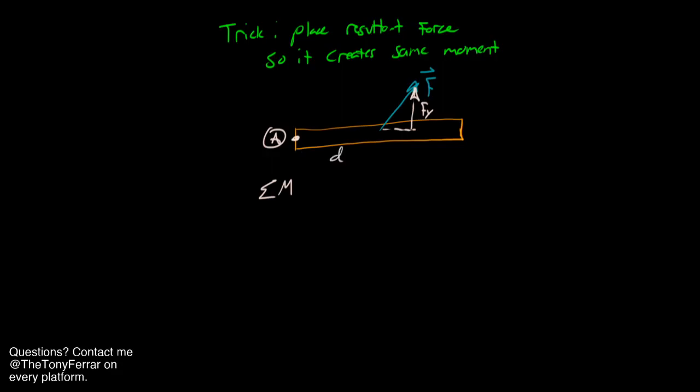We don't know what it is, but there it is, some unknown distance d, if we were to say that this force is applied along the beam. And so we could say that Fy times d is equal to that sum of moments. We could calculate both sides of this independently and solve for d, as the sum of moments over that force, and we could find out what location the resultant force would have to act at.